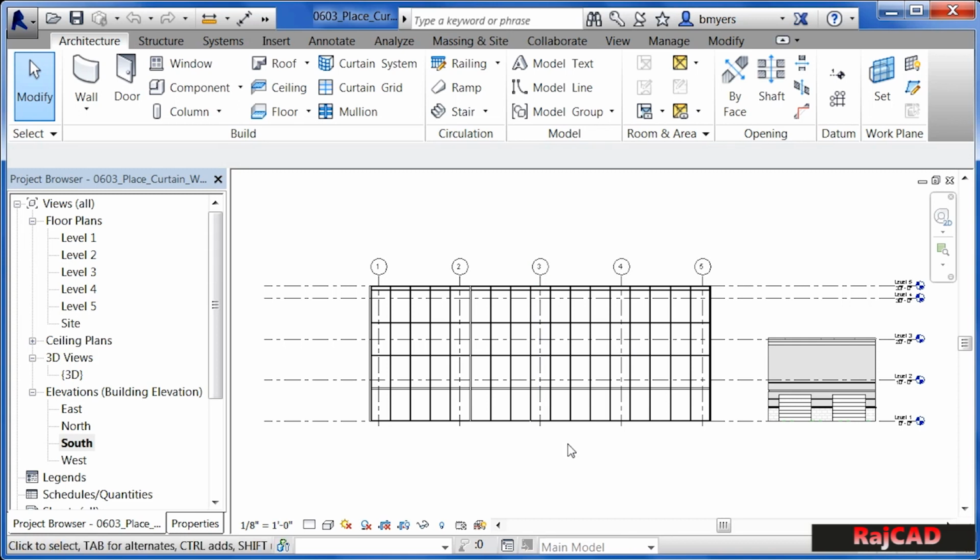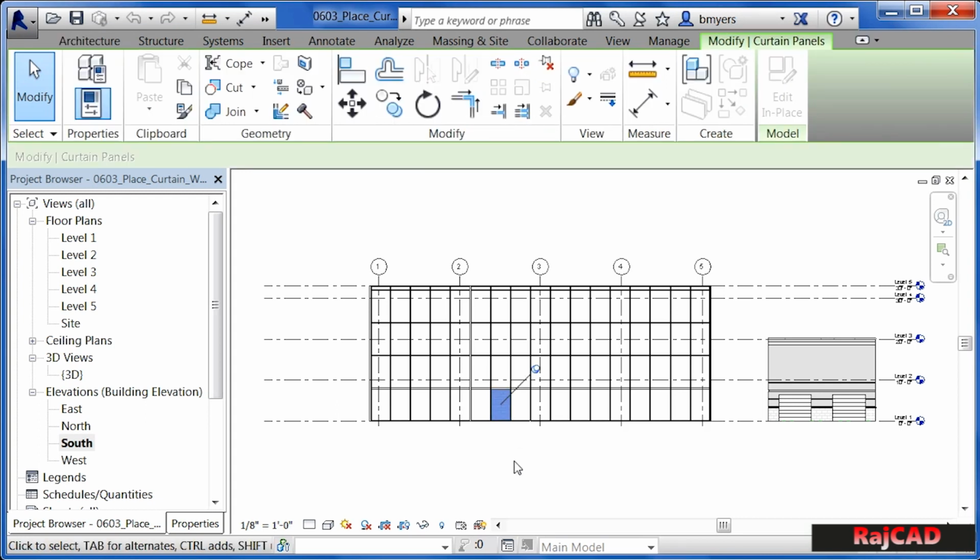As a result of that, if you're in Revit 2014, you'll have some pin tools over here. And this one is called Select Pinned Elements. Click on this button here if you're getting that music. It's not allowing you to select. When you do, you should be able to then move your mouse back up. More than likely, an individual mullion will highlight, just like mine is. And then if you click the Tab key on the keyboard, continue to do that until eventually one panel is highlighted blue all the way around that panel. Then just click in order to highlight it.